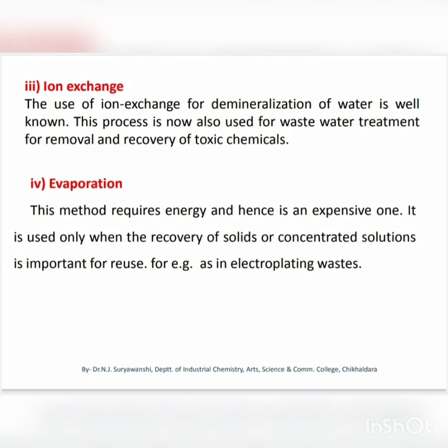Application of ion exchange for wastewater treatment involves the recovery of chromium, nickel, phosphate, and sulfuric acid from anodizing baths, recovery of copper, lead, and mercury from cooling tower, and removal of cyanides from waste streams.